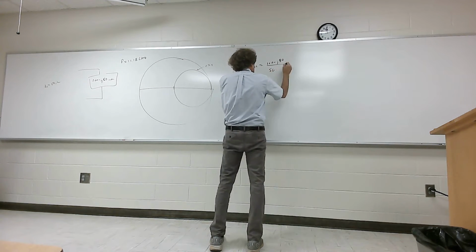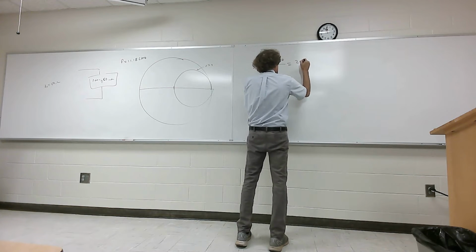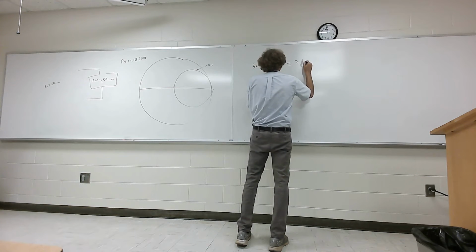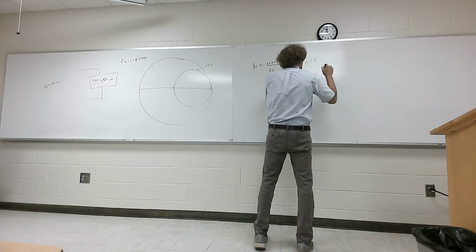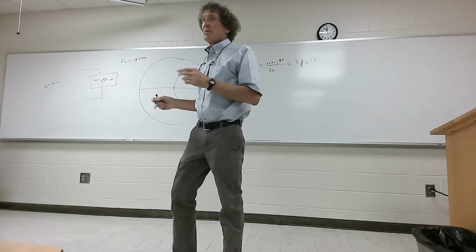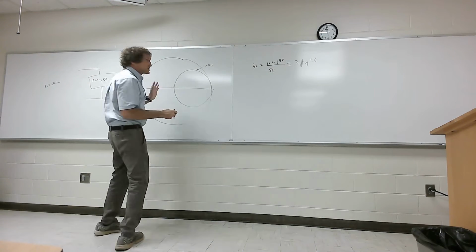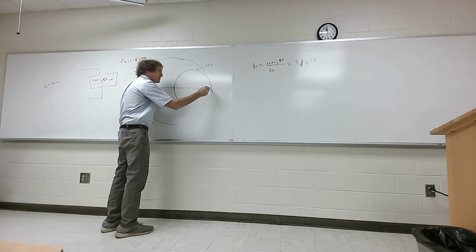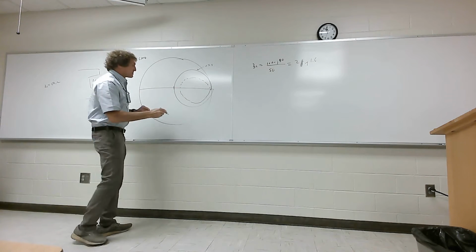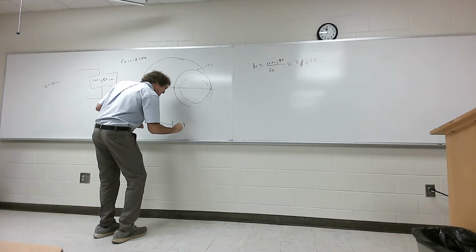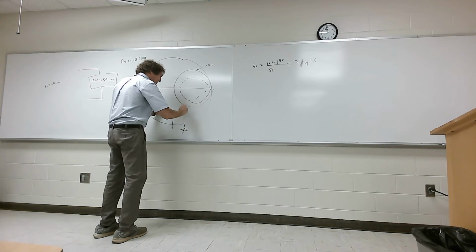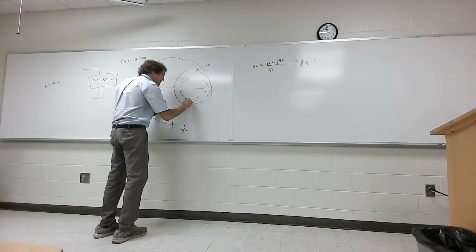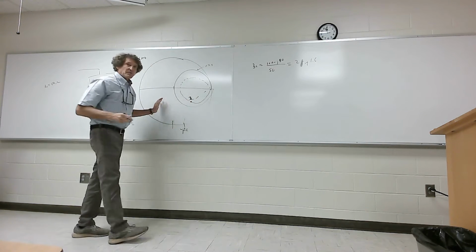That's 2 minus j1.6, right? Now we plot that. In this circle, it's inside the one circle. The 2 would be probably about there, but I'm just estimating. And if that's minus j1, this is about minus j1.6. So that would be zL, correct everyone?